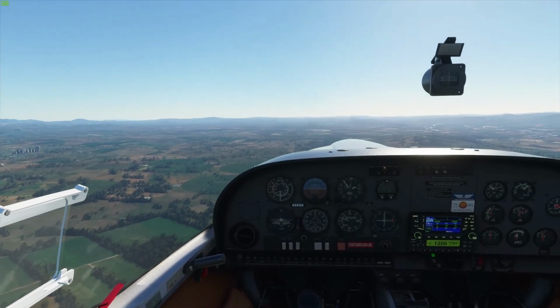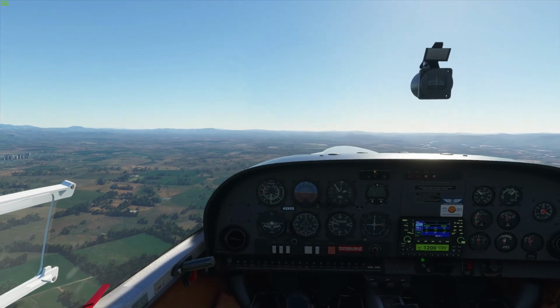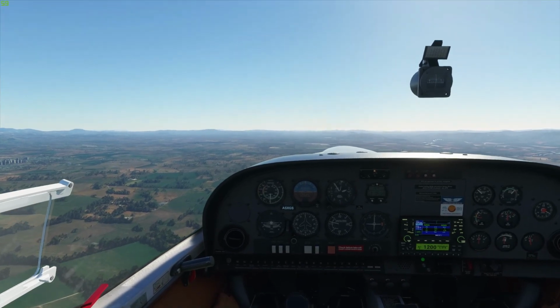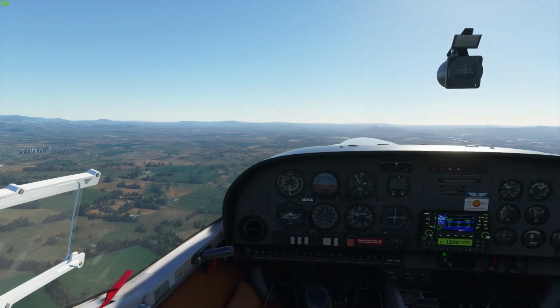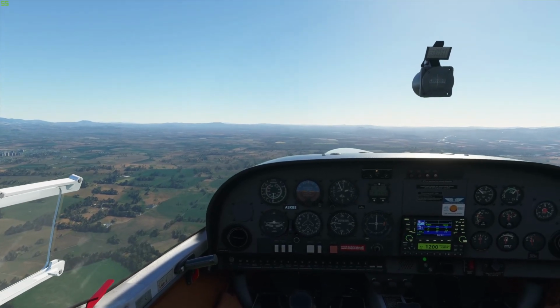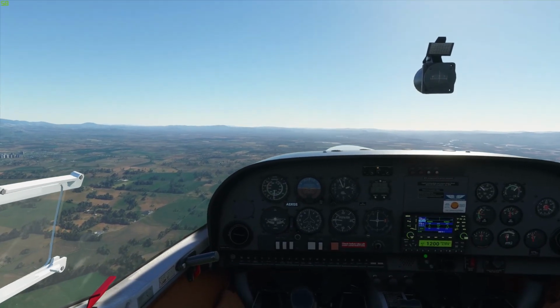And the idea with a Phugoid test is that we will essentially get the aircraft trimmed out for level flight for the power setting that we're at, and that should be around 100 knots or 105 knots as we had before.